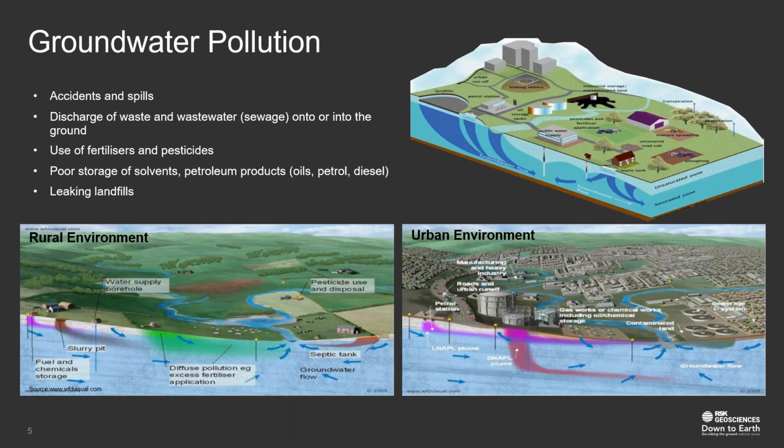Groundwater pollution: groundwater becomes contaminated when pollutants enter the subsurface. This can happen through industrial spills or leaks from fuel or oil storage, agricultural runoff, landfill leachates, wastewater discharge, abandoned mines, or leaks from septic tanks or sewers. Therefore, it is necessary to regulate these activities to control emissions and hence protect our groundwater. And if contamination does occur, groundwater remediation is necessary to protect both people and the environment.